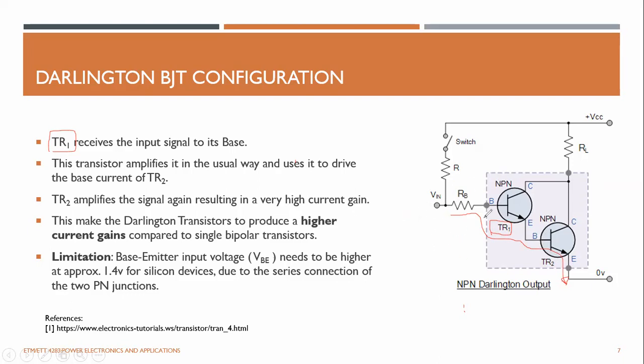So you can see this one is forward biased and this one is forward biased, right? With this one forward biased, it drives a small current from base to collector, which leads to a large current from collector to emitter of this transistor. This large current flows from here, but it needs to return through the emitter of the T1 transistor, right?